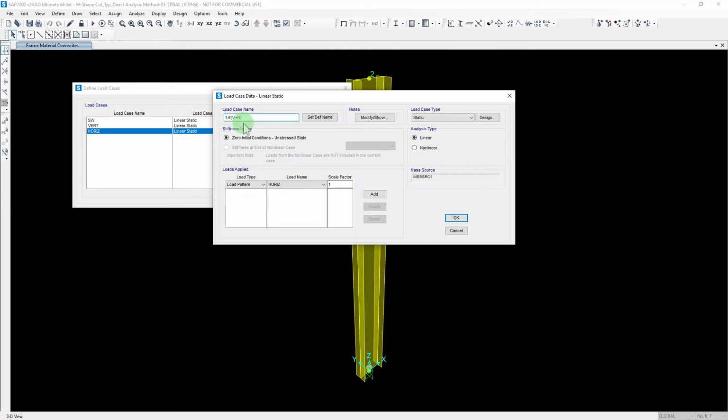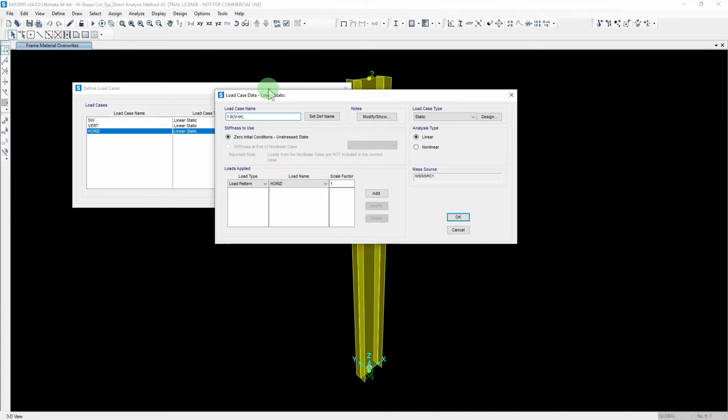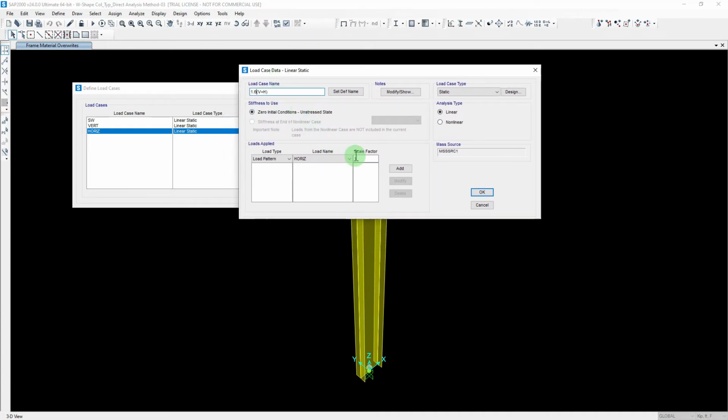It's basically related to the fact that I'm planning to use the allowable strength design method for this particular example. And in AISC, you will find that when you use the direct analysis method and you design a structure using the allowable strength design method, you have to use a 1.6 factor during your analysis so that you could analyze the loads at the strength level.